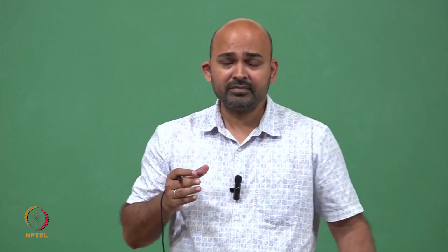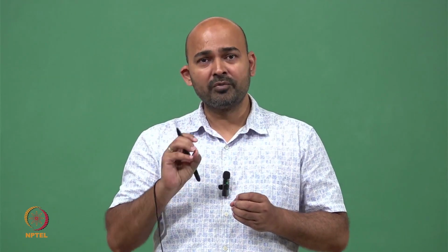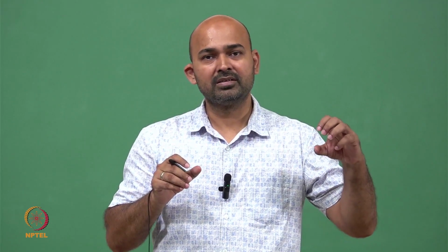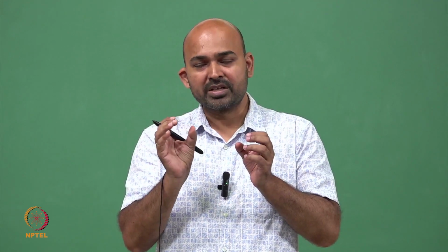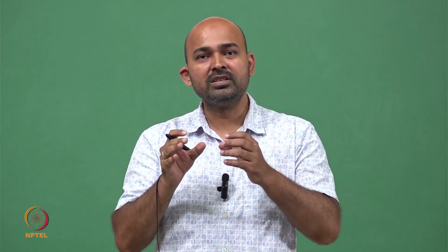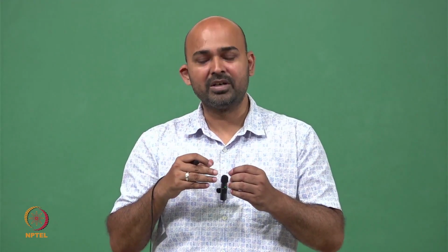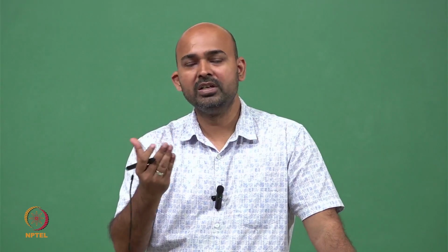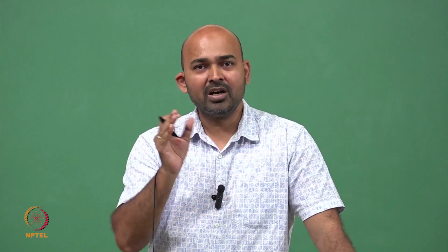Now, if this core material also has a certain amount of magnetostriction, meaning the size, the dimension of this core also changes with the applied signal at the primary, then there is a continuous compression and expansion, and this core loses energy to the outside environment in terms of mechanical vibrations. A very common example of this is when we go near a very big transformer on the street or somewhere, then we hear a humming sort of noise.